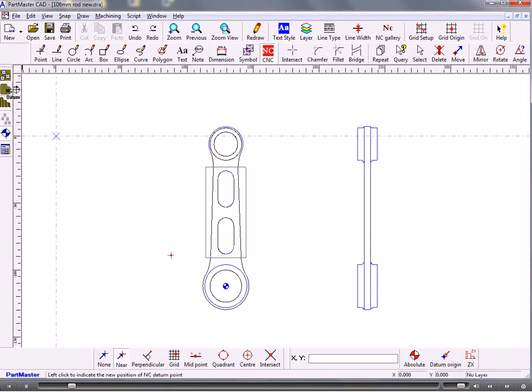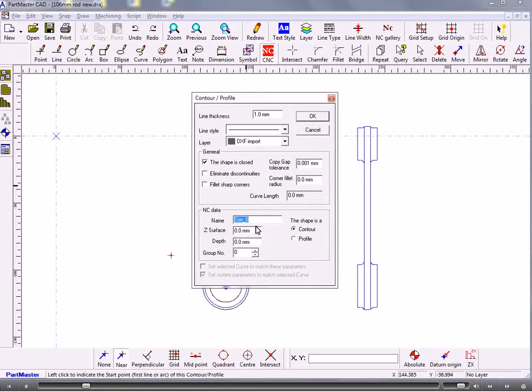So to do that we go into contour mode, and then we'll start off with these inside contours here. Okay, now if you look at the end view here, you can see how the shapes will need to have different Z depths and different origins in Z, so that we're not machining in fresh air too much. Okay, so if we're going to do that, let's do this rectangle first, and we'll set that to be at Z0, and the depth is whatever depth it needs to be.